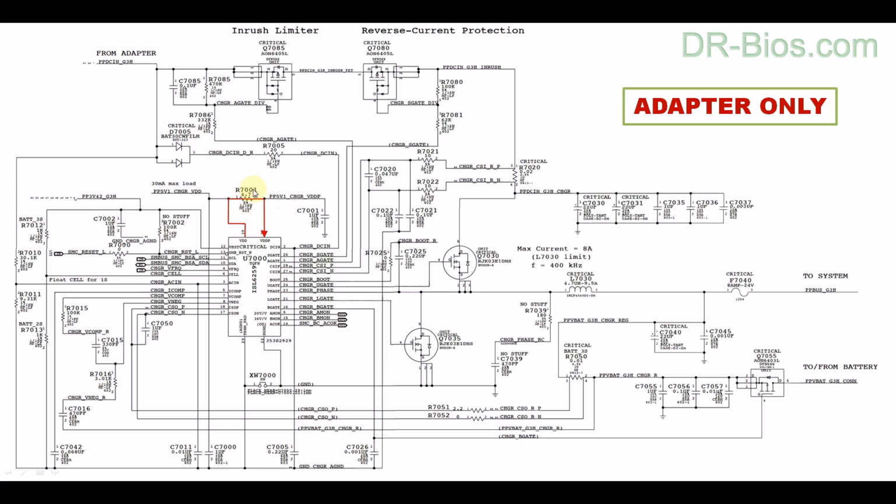And after passing through a resistor which is R7001, it enters VDDP pin. This voltage that is generated by the IC is consumed by the IC only. And when the IC receives VDDP voltage, it disconnects ACOK signal from GND.